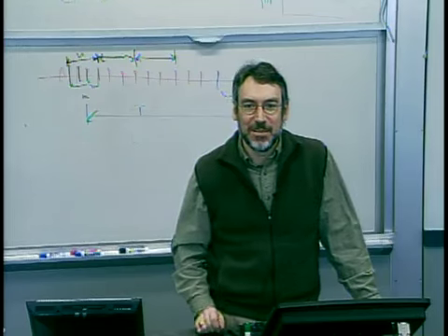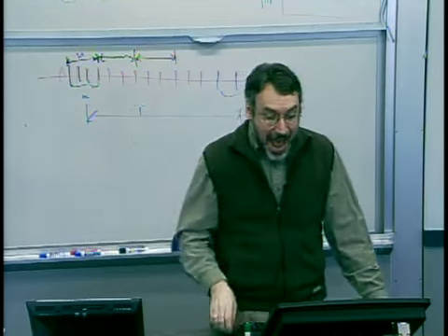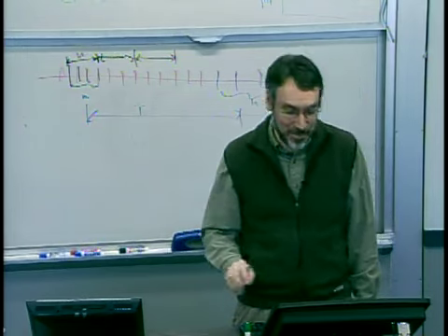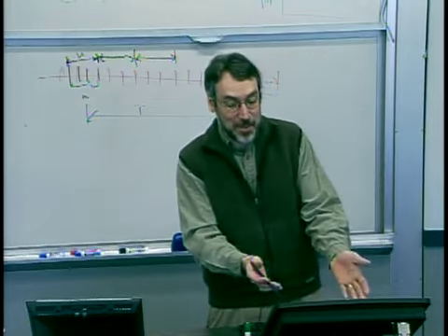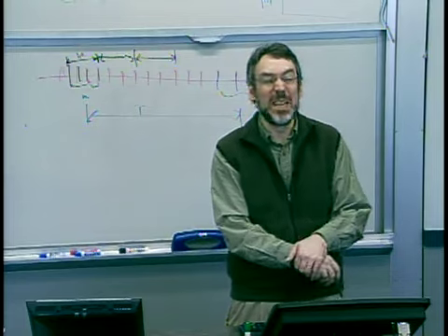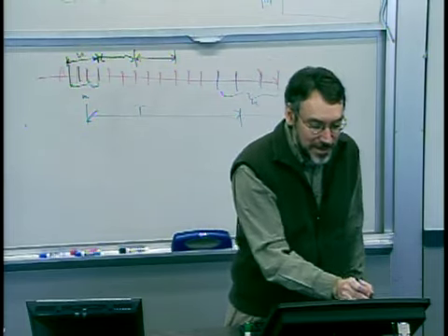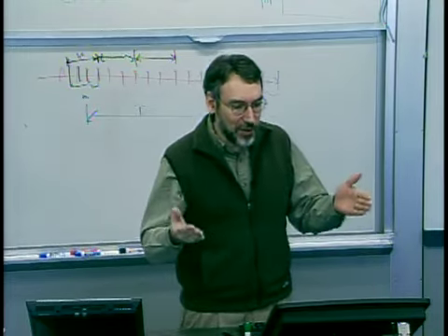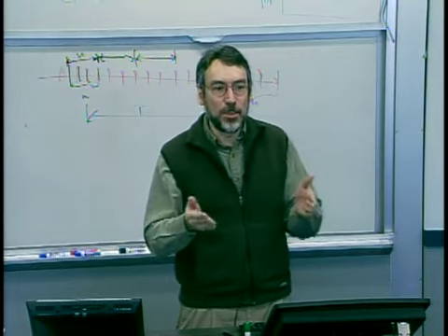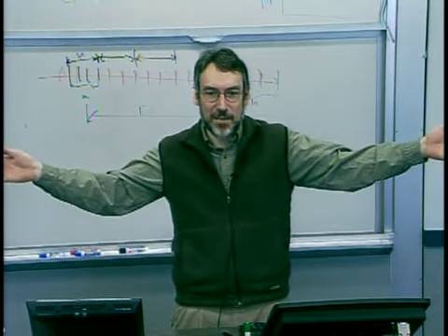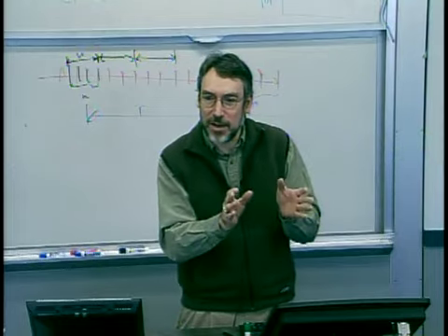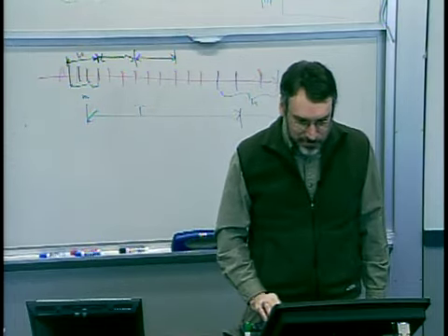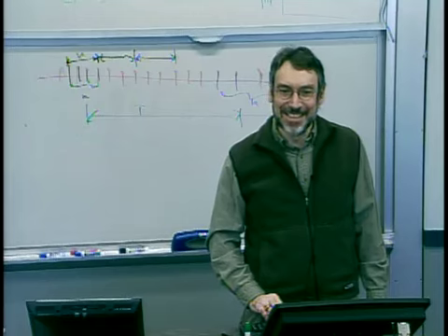Wouldn't it normally be safe to say that you want your spec limits outside your control limits? Absolutely. So, why? Here you're having a huge fraction of non-conforming. Yeah, that's my point. Your spec limits may be very tight, and your process would be horrible. This is not a capable process. So normally, yes. What you normally want to do is trigger on alarms much before you have parts that are falling outside of spec, so that you can react to drifts in the process before they cause you disaster. Absolutely. That was implicit. I'm glad you made it explicit. Yes, yes.